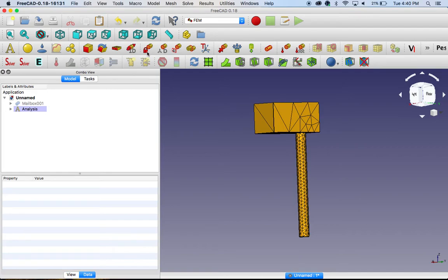This little one here that has a lock and this one that has an arrow. Now the lock is called a constraint, meaning if this mailbox is obviously planted in the ground, there's one portion of it that's not going to move very much, and that would be that bottom section down here. So the top is a rigid structure. But if I were to push at the top of this with my hand, it would probably move a little bit. But if I pushed at the bottom of this pole, it's not going to move at all because it's fixed in the ground. So we need to tell the program that that's the case.